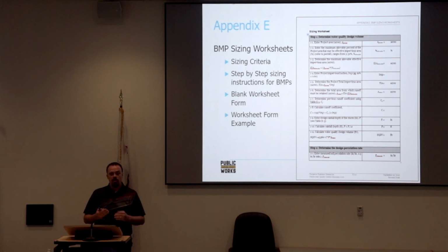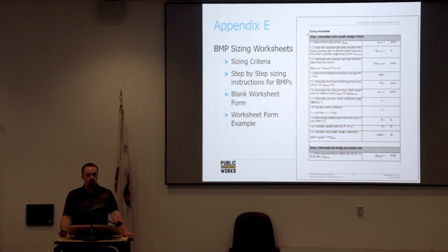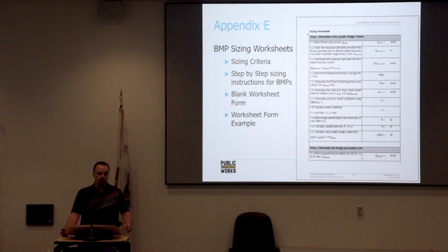a filter bed you're going to be doing, what is the ponding depth, that surface you're going to incorporate, and all those things directly relate to the details on the plan. So we can compare and contrast as we go through reviewing it, but it also helps the designers appropriately select and size these BMPs. With these, there's also the blank forms that you can utilize, and then there's an example filled out for each one, identifying, okay, for a site of 10 acres, this is exactly how it's filled out. These are the numbers, so you can check your own numbers as you go.